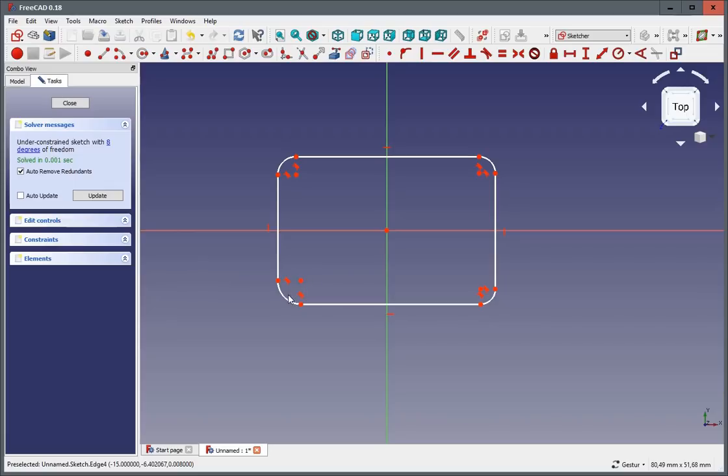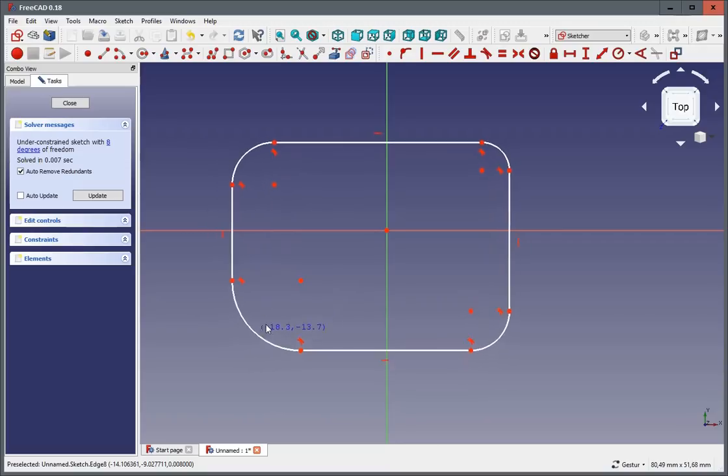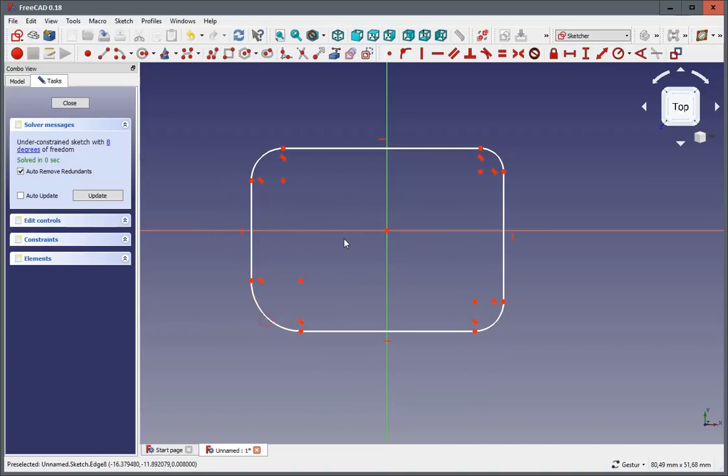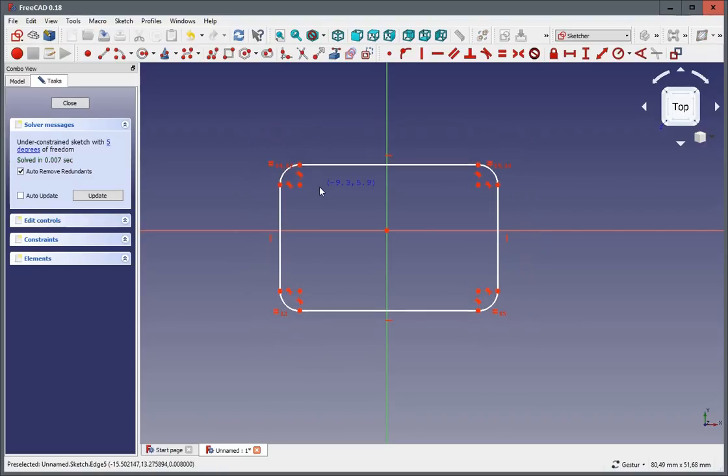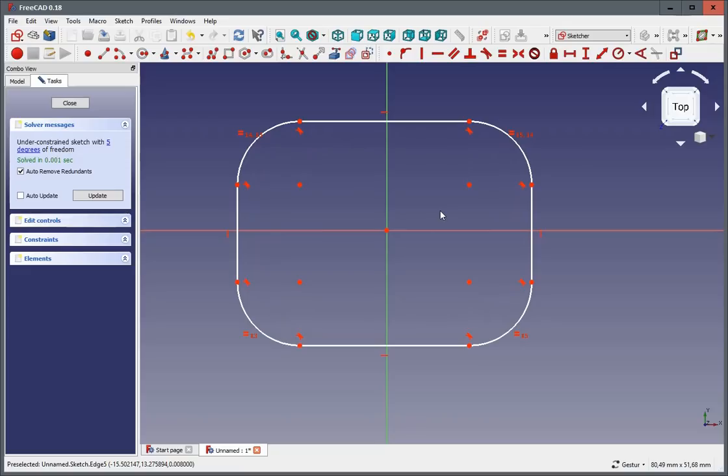When we now go and change the radius of the fillets, likewise by dragging, or if we select them and we want to just say make them all equal, then we see the size of our rectangle changes, and it changes heavily. So how can we assure that our base construction stays the same whilst we can change the radius?